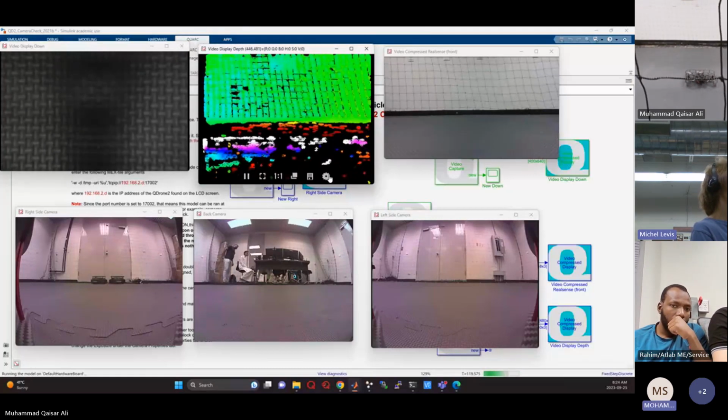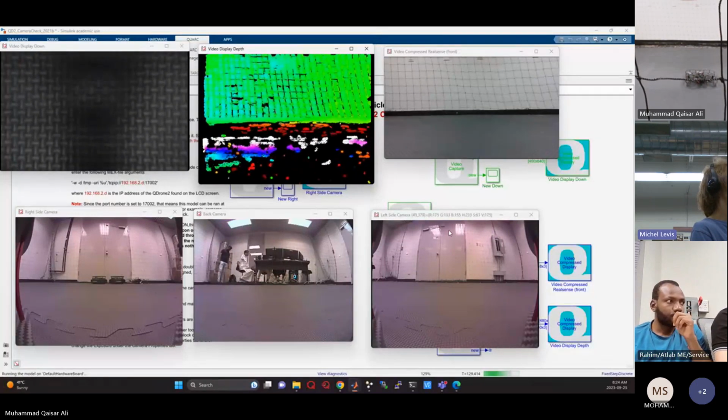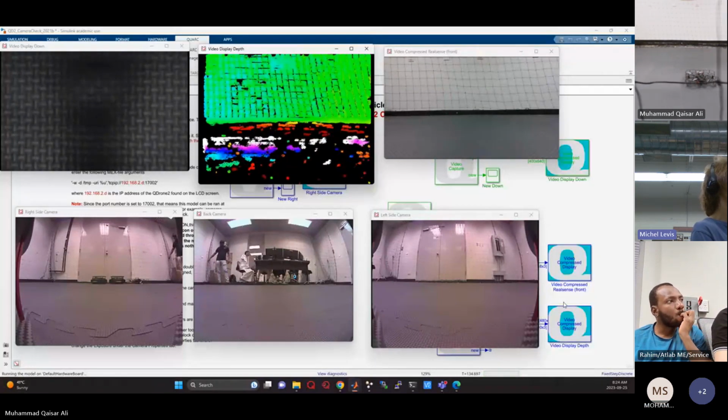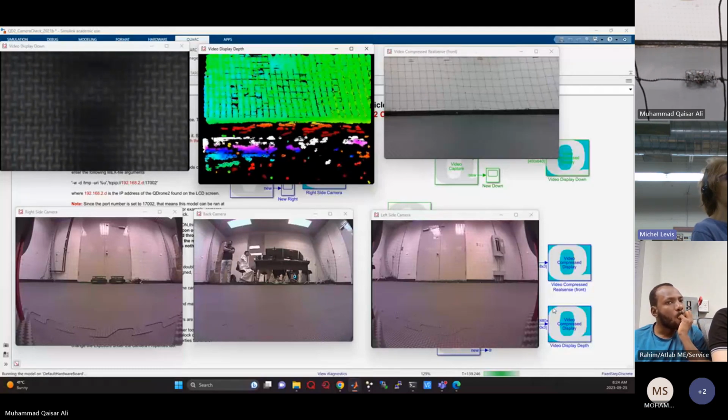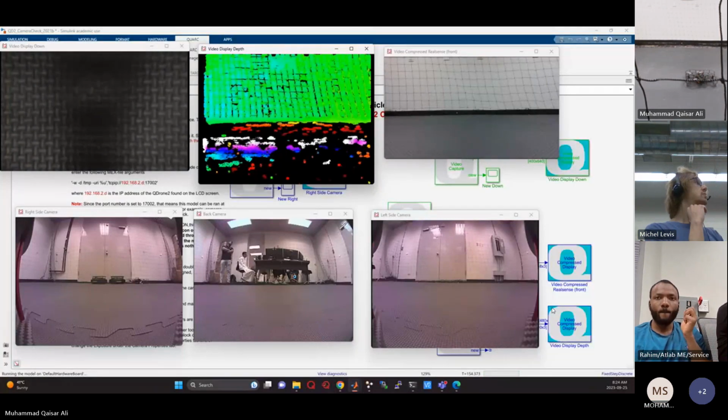So yeah, guys, this is a lot like the Q car, right? The left, right, and back cameras are the CSI cameras, and then you're getting the OmniVision, which is the downward-facing one that's used primarily for optical flow, as we've seen with the Hill Read block, and then the front camera is your Intel RealSense RGB and depth camera. The depth measurement is just like in the car, passed through that colorized block to give you an indicator of which objects are far, which objects are close.